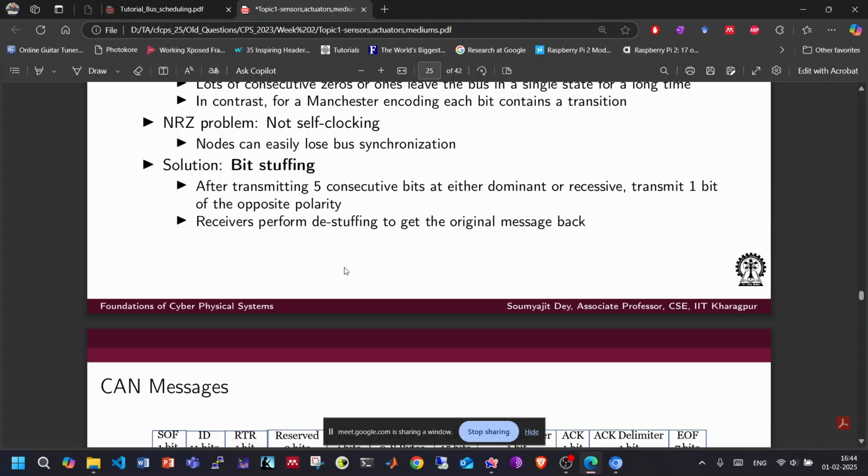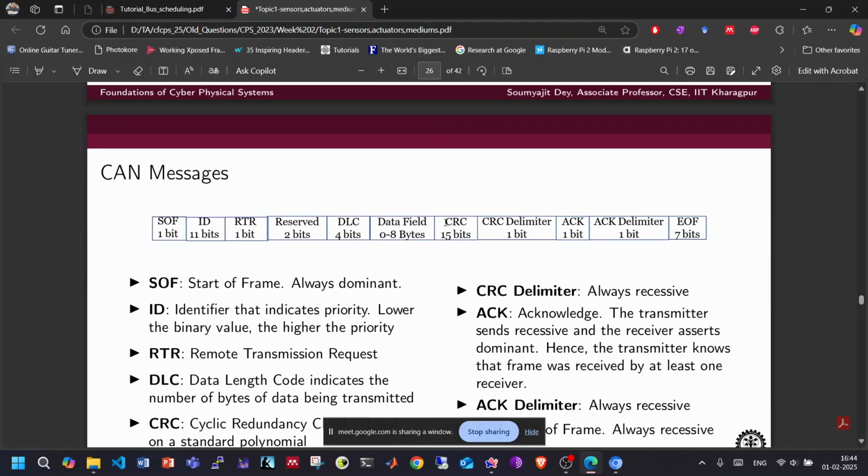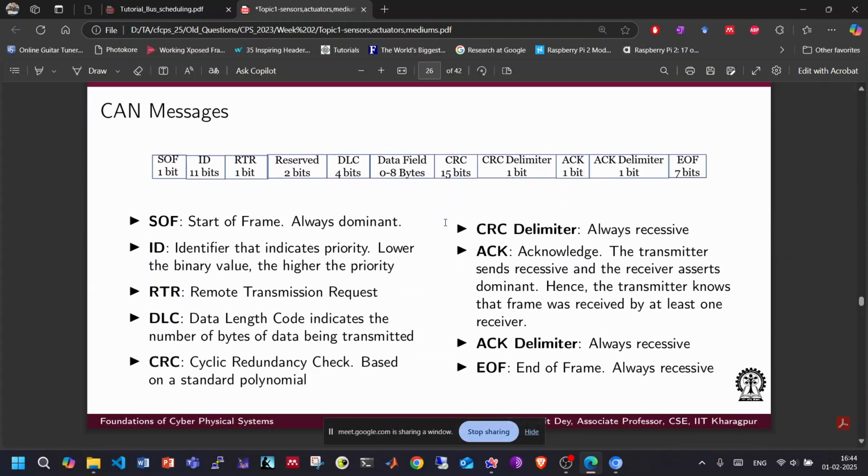So when you are toggling, basically this is what it says. If there is a signal that you are transmitting, you easily understand it. If there is a toggle after 5 bits, you will easily understand that it was the same data actually. And if there is a toggle, obviously there will be a toggle and the bit will stay there. Since it is a non-return to zero, the bit will stay there for longer. So you will understand which data was there. So it won't be an issue.